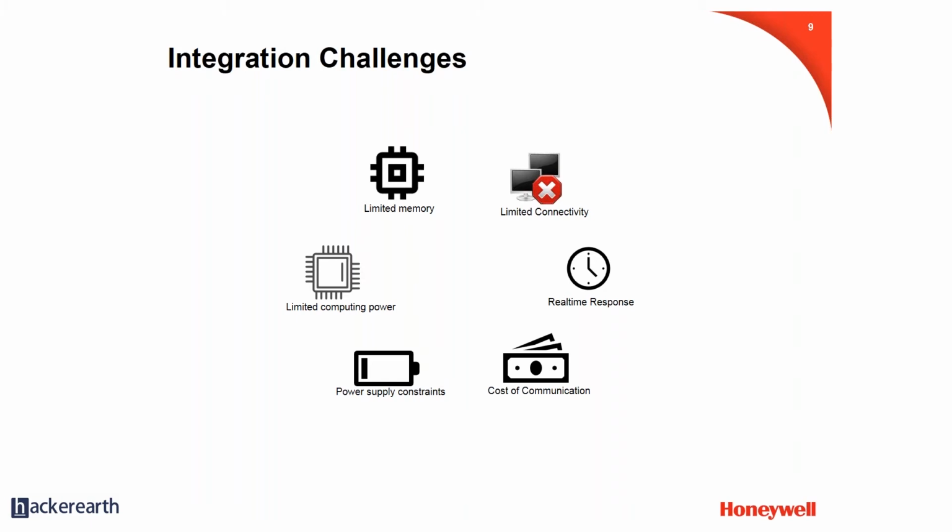And then you have limited memory, be it the RAM or the flash. So the size of the application you build, the size of your firmware, has to be extremely tight, and you have to be very judicious in the use of your data structures. Your runtime memory is extremely limited. These present unique architectural and design challenges that you have to be very aware of, because for people who are not from an embedded background, these constraints can be very novel. These are not things you typically run into when developing applications on the cloud or even on a PC. So these are some of the integration challenges that one should bear in mind.